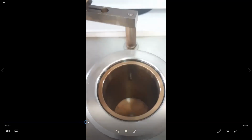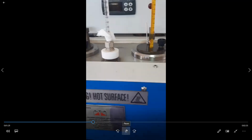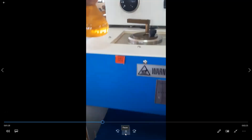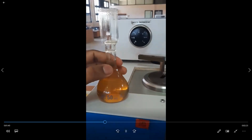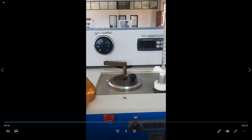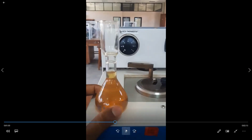we will collect this oil sample from the bottom side. At the same time we will measure the time to collect 50 milliliters of oil sample. This is the bottom side, and from here we can collect. This is the 50 milliliter flask, the first sample for which we are going to measure the viscosity. This is new oil.